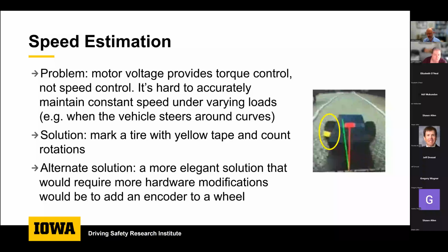Maybe it would be different if we were on a wood floor or a smooth floor, but on the carpet, it made a big difference. So it became kind of nice to try to compensate for that using this speed sensor. That way, when we can tell that the speed is really slowing down, we can increase the command a little more.